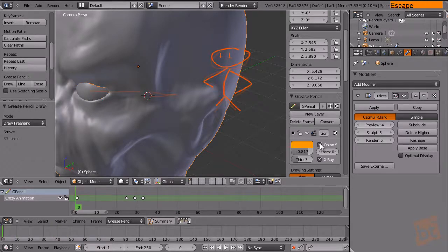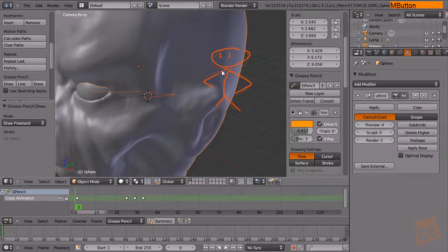We can deactivate onion skinning. Onion skinning lets you see the previous and after frames, alright? So you have them as a reference. Here you can select the range of the frames that will appear, as you can see, right? Zero is endless, alright? Every frame will be shown here. So deactivate it and you can see the actual animation.